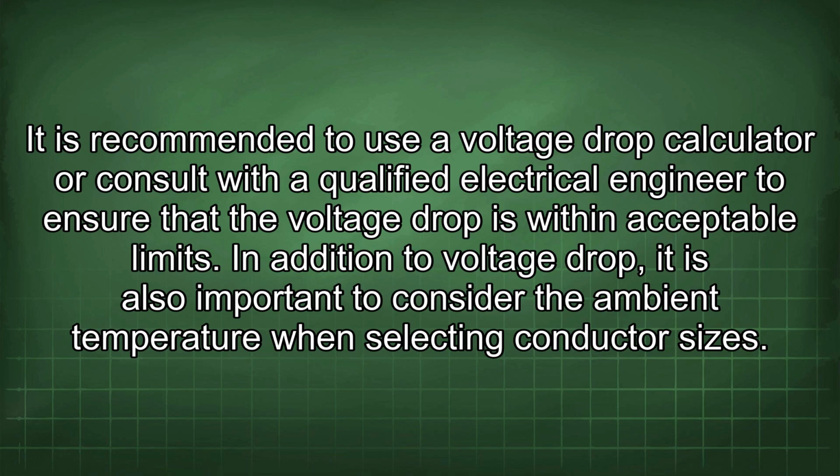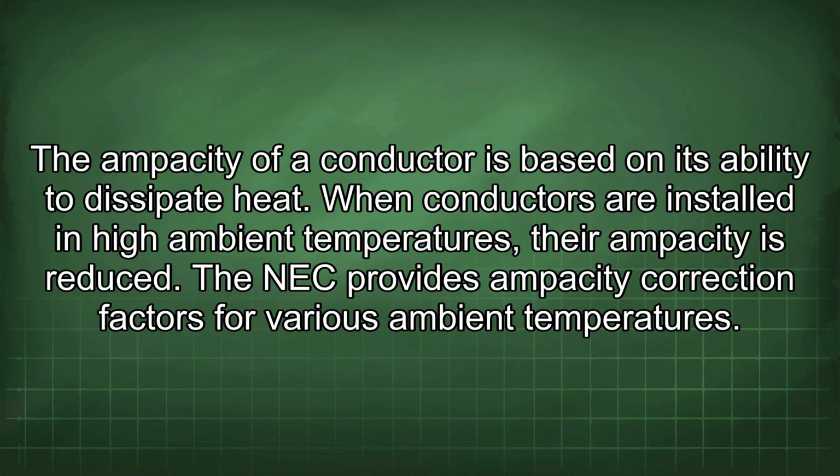In addition to voltage drop, it is also important to consider the ambient temperature when selecting conductor sizes. The ampacity of a conductor is based on its ability to dissipate heat. When conductors are installed in high ambient temperatures, their ampacity is reduced.